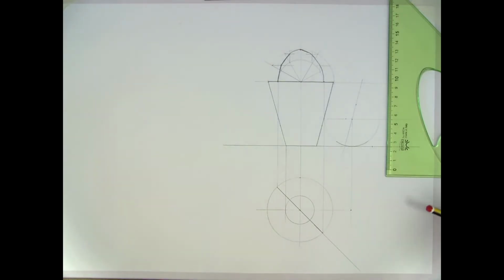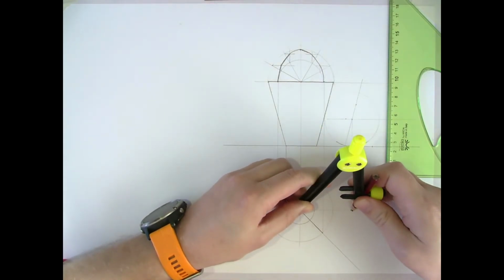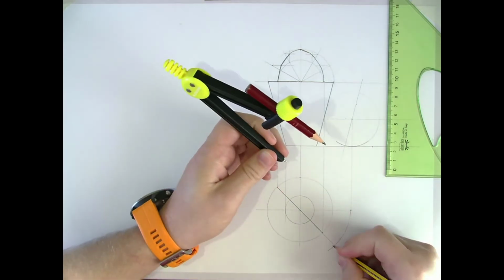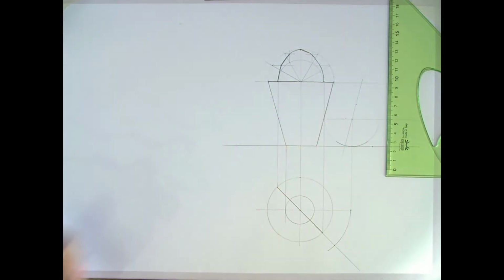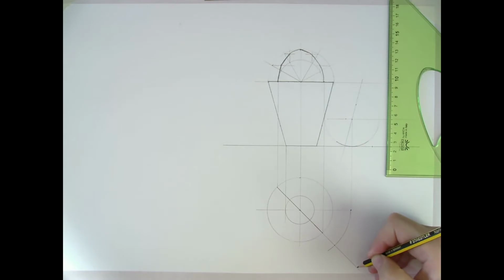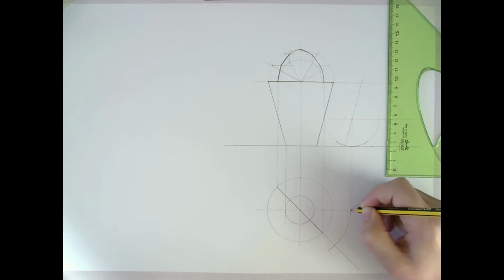So I can take that distance now. I'm going to rotate that around the side of the cone into this position down here, and this is the center that I'm looking for, for that sphere. Reason being, it's in the correct line coming down along this way, and it is also this correct distance out from the edge of the cone so that it's in contact with it and it's not cutting through it.